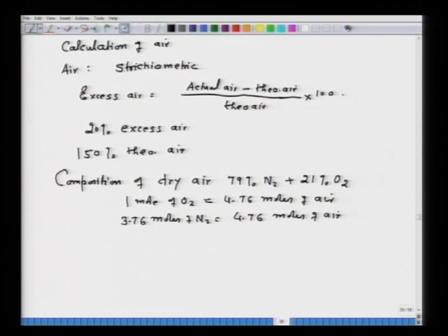Now, also the temperature raised by products of combustion is called adiabatic flame temperature, and this temperature can be easily calculated if required for the heat balancing operation in unit processes by doing the heat balance, heat input is equal to heat output. Now, all these illustrations are given in detail in my video lecture course on fuel, furnace and refractory. Here I have just given a very brief account as required for calculation on the material and heat balance in case of unit processes.